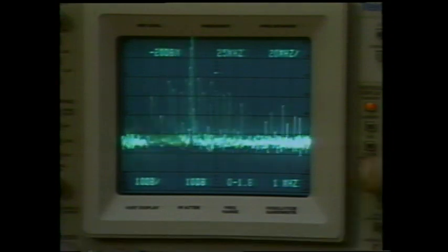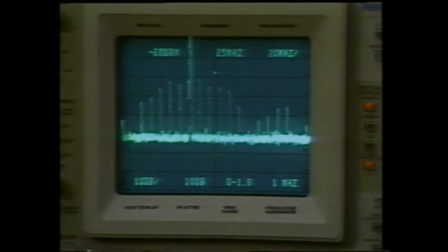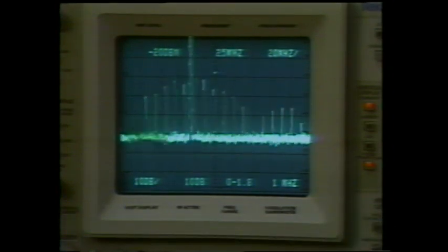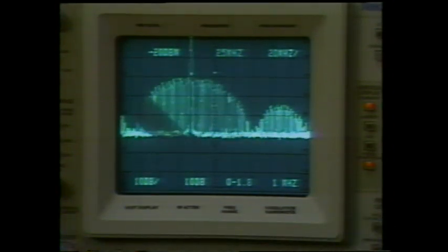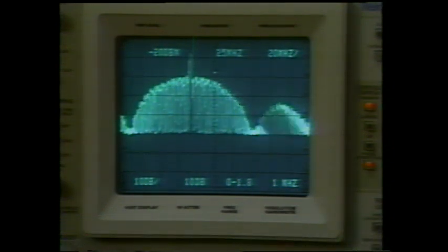To help the digital storage, turn on the pulse stretcher. In fact, it's a good idea to always use the stretcher. For very low rep rate signals, use max hold. With digital storage, max hold helps you get a clean buildup of the shape of the pulse spectrum.